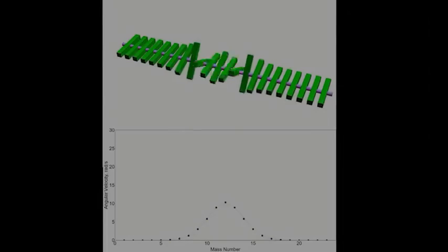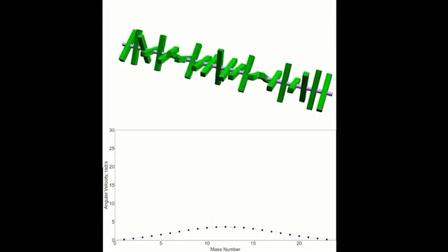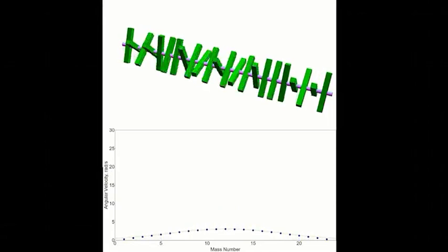Since electrical and mechanical systems are equivalent, it means that there is a mechanical system that is equivalent to the diffusion equation as well. In fact, one mechanical analog is a series of spinning masses with torsional damping between them, where we focus on the state v and how an initial velocity in the middle diffuses to velocities throughout the system.